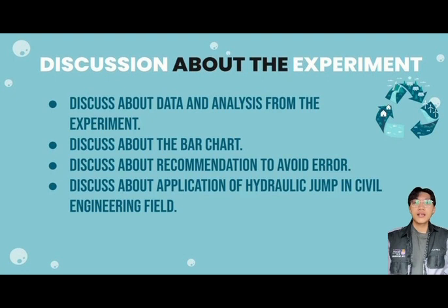Based on the results and analysis that we have done in the analysis part, there are a few data that we collected from the experiment. They are height of sluice gate, volume of water, time, height before the sluice gate, upstream depth and downstream depth. All of these data are very important to make the analysis for this experiment. For example, to find the discharge, we can divide the volume of water by time.